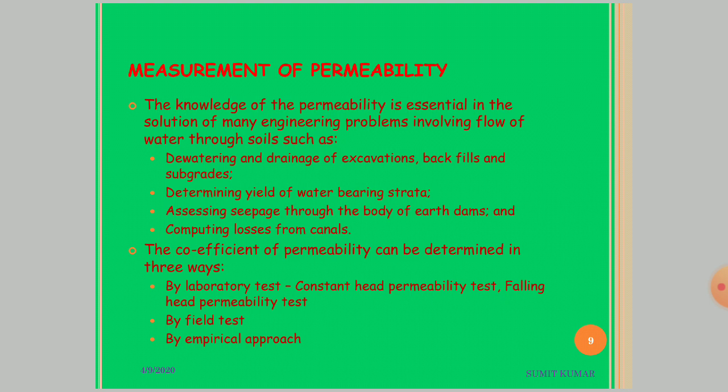The knowledge of the permeability is essential in the solution of many engineering problems involving flow of water through soil, such as dewatering and drainage of excavations, backfills, and subgrades, determining yield of water-bearing strata, determination of seepage through the body of earth dams, and computing the losses from canals.